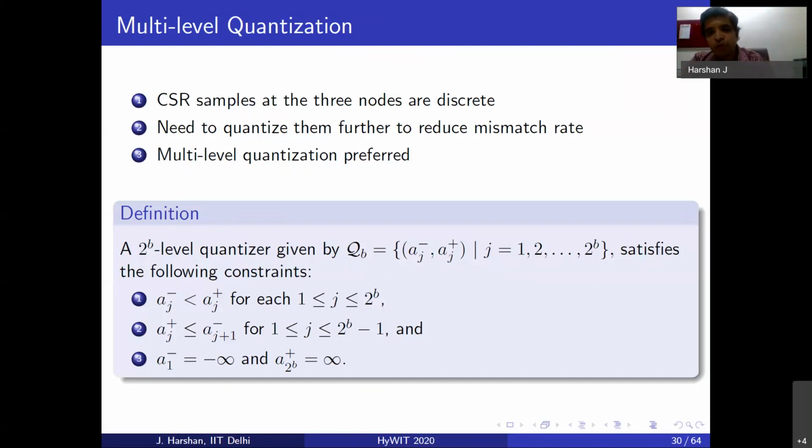So what we want to do now is further quantize these samples into multiple levels, but the number of levels that we would now use has to be carefully chosen. The simplest that I could do is partition this into two groups, so that I'm only going to extract one bit out of a sample. To generalize that, I'm interested in extracting B bits per sample. So in the dynamic range of these QAM symbols, I need to identify 2 power B such regions, okay? And once I have these 2 power B regions, we also need to decide how to really draw the boundaries here. Going by the basics of guard bands that was discussed in the preliminary part of the 2-user key generation, these boundaries are not just thin lines. These are thick lines which are called guard bands because we want to arrest some of the errors that would creep in from one region to another, right?